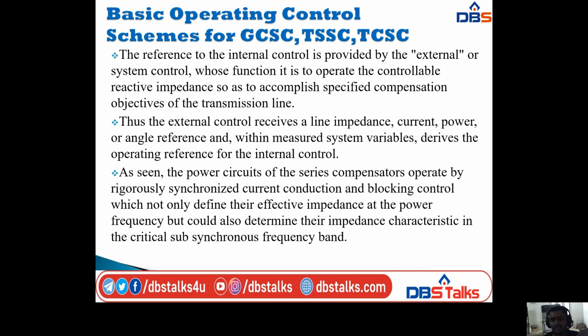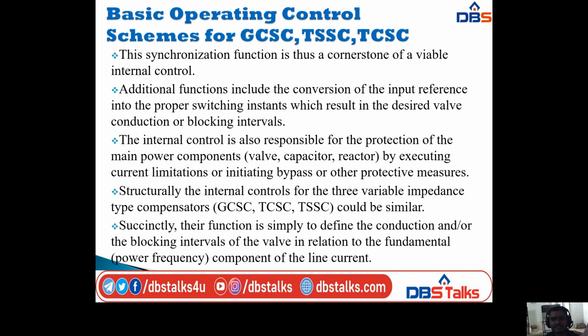So as seen, the power circuits of the series compensators operate by rigorously synchronized current conduction and blocking control, which not only defines their effective impedance at the power frequency but could also determine their impedance characteristic in the critical subsynchronous frequency band. So the synchronization function is thus a cornerstone of a viable internal control.